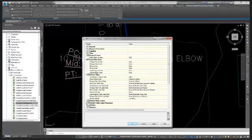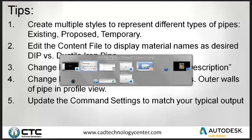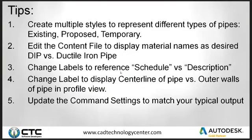And my biggest pet peeve is that they set these defaults so that anytime I create a part in profile view, it doesn't automatically label it. Well, guess what? Here, label a pressure pipe in profile view. Change it to true, make the saves. Setting up the command settings, going to that content editor, another way to customize your parts, and then just creating labels referencing different parts of that content editor.